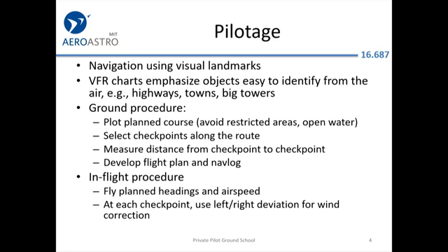So you say, look, I'm going to fly this. I'm going to be going 100 knots over the ground. I'm going to be blown off course very slightly by a crosswind from the north. You plan all that, and then you've got your nav log. So as you reach each checkpoint, you can make a correction. Well, it took me a little bit longer to get here. I'm a little bit left of where I thought I was. So you can make these corrections as you go along.